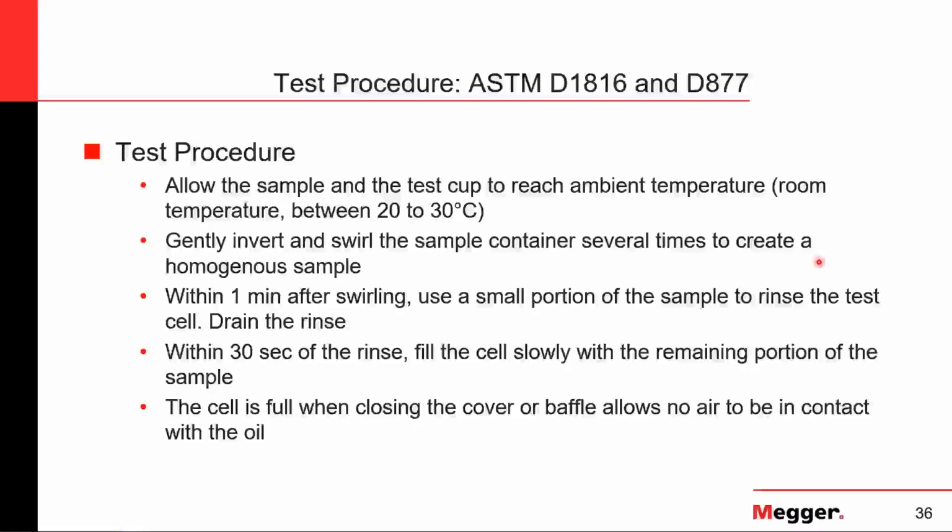And from here, I would say most of the equipment in the market will continue to do the test automatically, right? For ASTM D1816, we have a 3-minute waiting period between when we just finish the first filling to the first application of voltage. And again, most units will do this automatically.